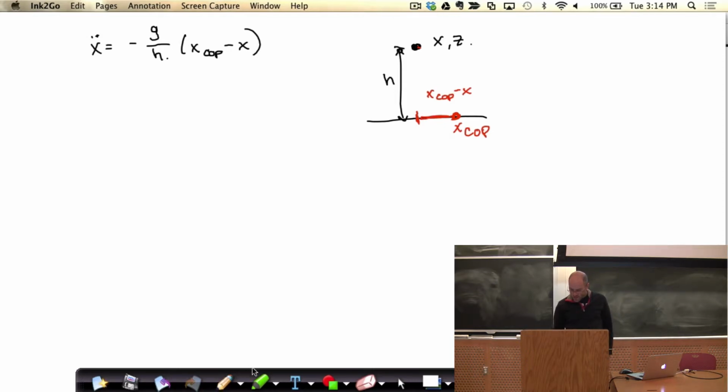Okay, so why does this matter? Why does this help? Well, first of all, I wrote a lot of sort of complicated constraints on forces, right? If I have friction on each potential force and they're in different locations, I've got r cross F everywhere. I can simplify this whole thing. I simplified the constraint on the center of pressure to be inside the support polygon. That now implies a very simple constraint on my acceleration.